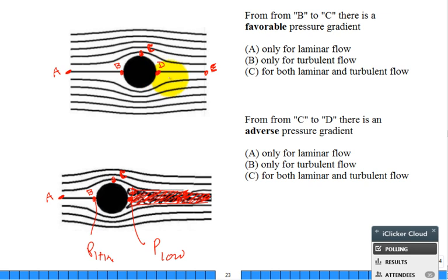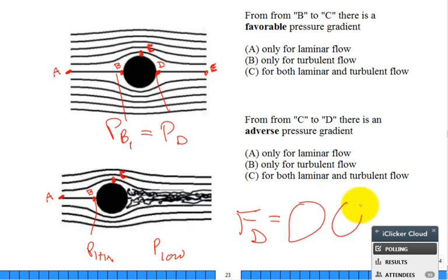When you have Stokes flow, guess what the pressure at B is? The pressure at B compared to the pressure at D. Full pressure recovery. They're the same. But now you start to get the pressure. So when you look at the net force, I'm trying to draw a force here, F, the net drag force, it's the sum of two components.